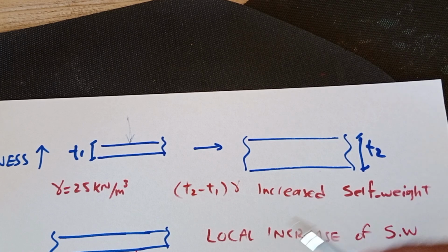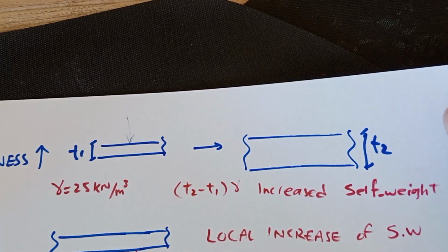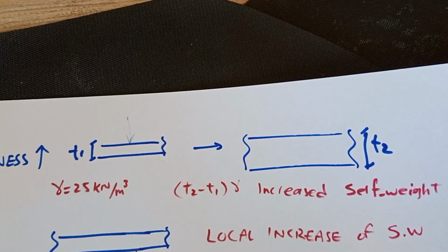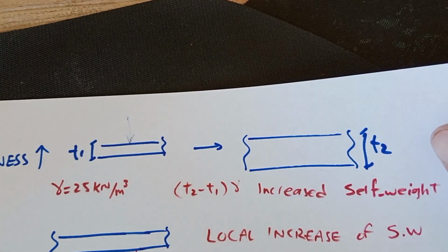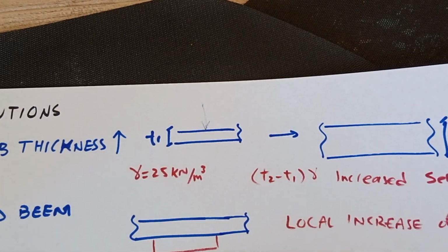It is a huge load, and we need to care about that when we go for the solution of slab thickness. We're increasing the capacity for stiffness and deflection, but at the same time, we're increasing the applied dead load.